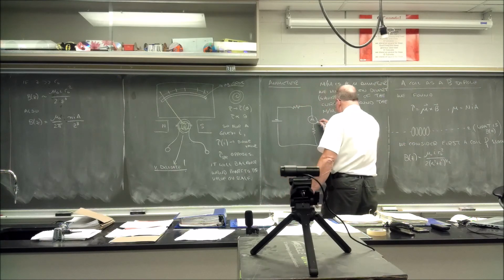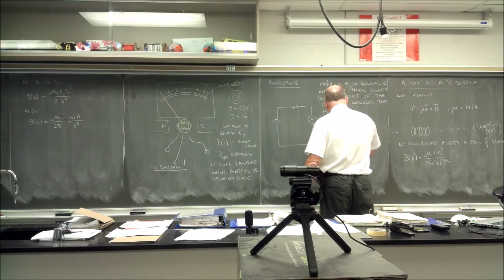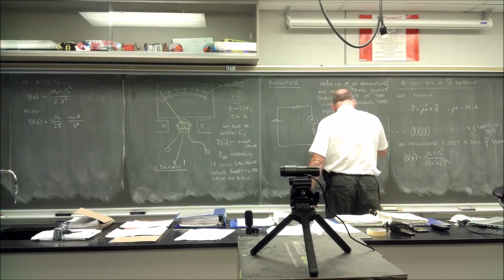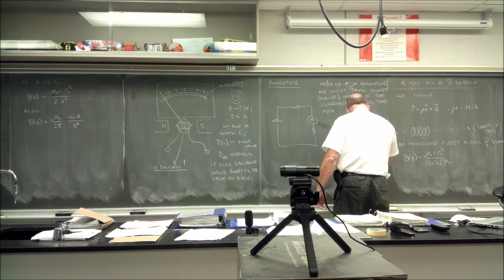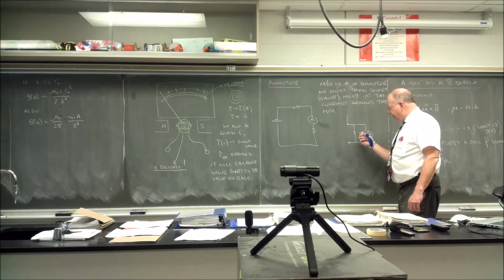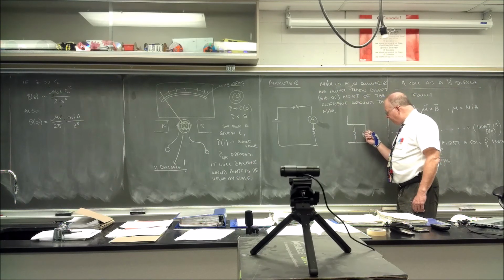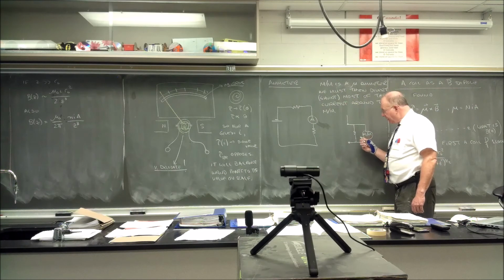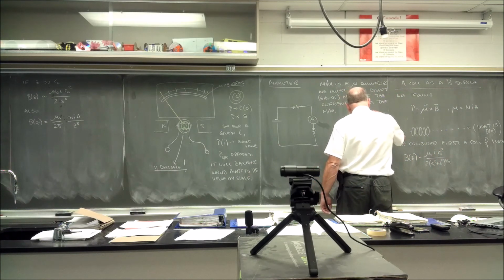So what we do in here is, the expanded view here, the wire will come in, and then here's our meter movement doing its thing, and here we have a resistor in parallel, like so. And we want the current to flow through this guy. And there'll be a parallel portion that flows through here that we can use to sense. We want to send most of this through here. So this is what we call our shunt resistor.